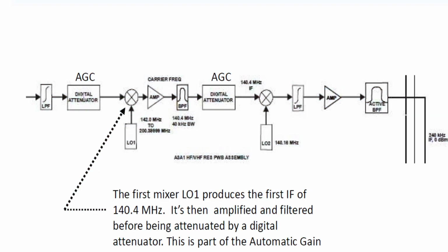So that's exactly what your AGC is going to do here, right? So with TGC, it kept the varying voice levels constant for the antenna, right? Because you transmit out the antenna. Yes. So the AGC is going to do the same thing, except it's going to keep those varying voice levels constant for what? What do you listen on? On the handset. So it's going to keep it constant for the handset. So when you hear that person's voice coming back through to your side of the radio and you receive that signal, it's not going to be all over the place, and it's not going to sound all squeaky. Make sense?